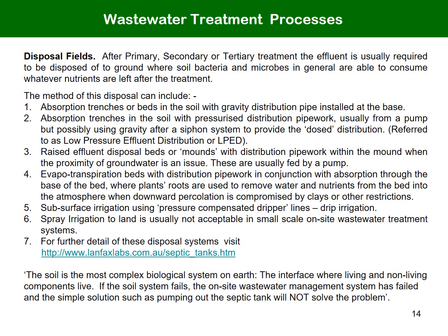Raised beds or mounds with distribution pipework are used when the proximity of groundwater is a seasonal or permanent issue. Raised beds are usually fed by a pump. Evapotranspiration beds often incorporate sand to aid transportation of the liquid to plant roots. In these beds, transpiration of liquid by plants to remove water and nutrients is used, as well as absorption of liquid through the base of the bed, particularly where downward percolation is compromised by clay or other restrictions.